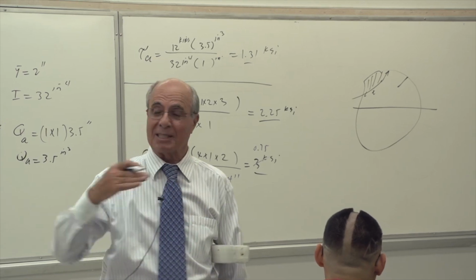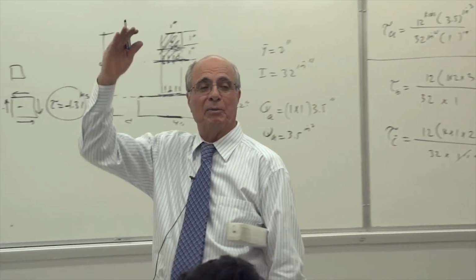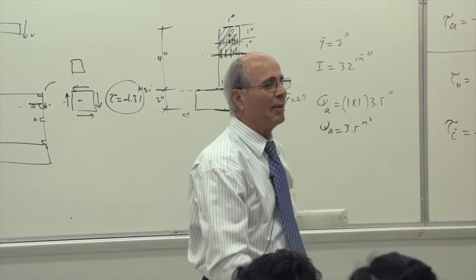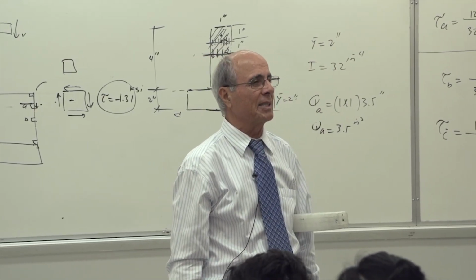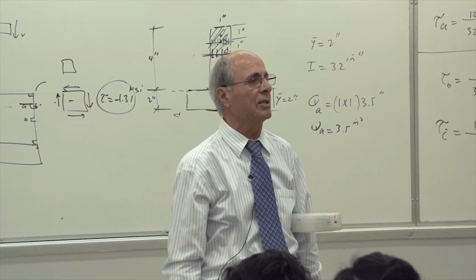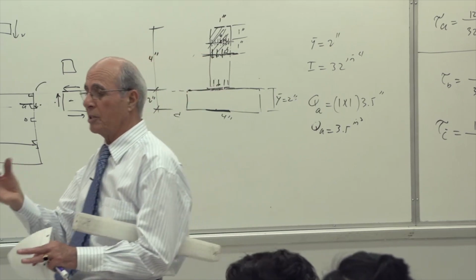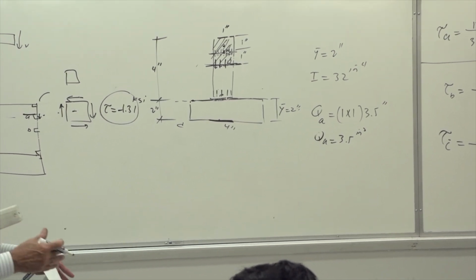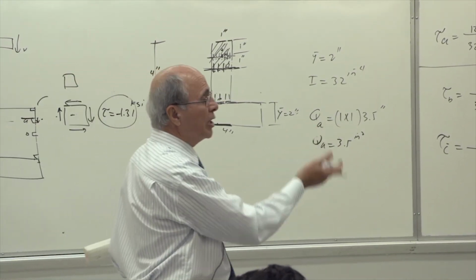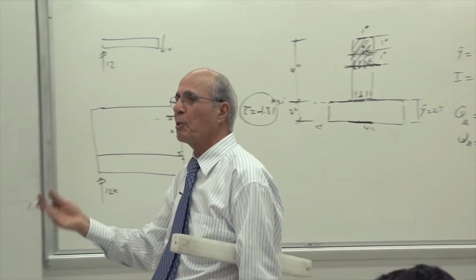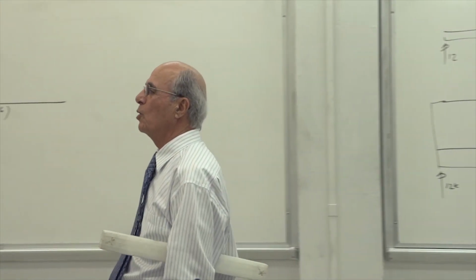Yes, because the stresses, remember, horizontally were constant, vertically keep changing. So I make a cut like that. Who wants that average of that shear stress? That doesn't make sense. But that was for the purpose of saying that you can do that. Is that correct or not? The piece has to be, write it down in your notes, totally separated. The piece being separated will be the Q. The length of the cut, where the knife is cutting it, will be the T. If you do that, then all of the other problems become simply following that rule.